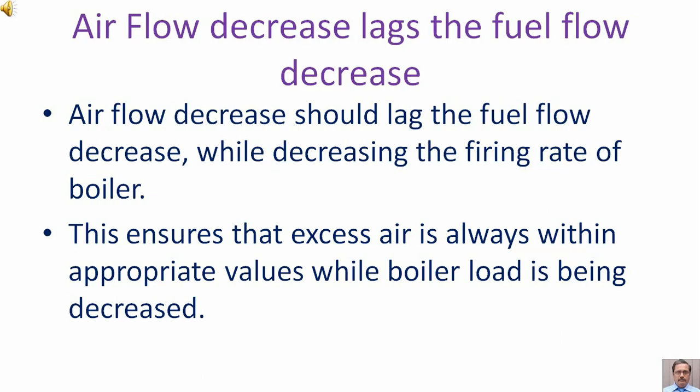Airflow decrease lags the fuel flow decrease. Airflow decrease should lag the fuel flow decrease while decreasing the firing rate of boiler. This ensures that excess air is always within appropriate values while boiler load is being decreased.